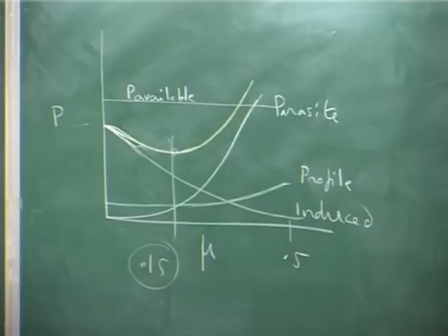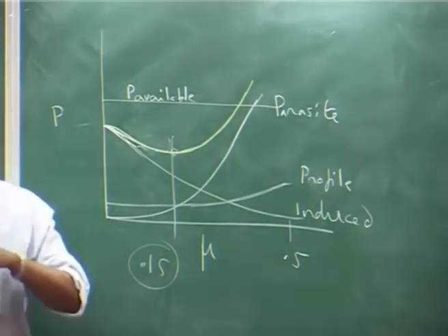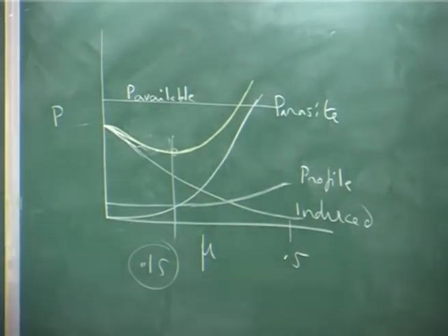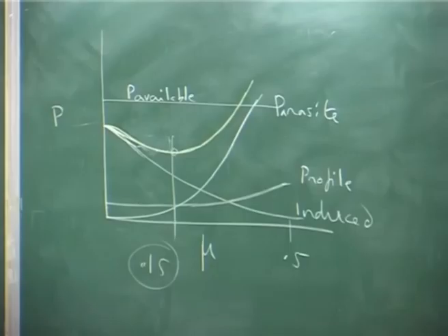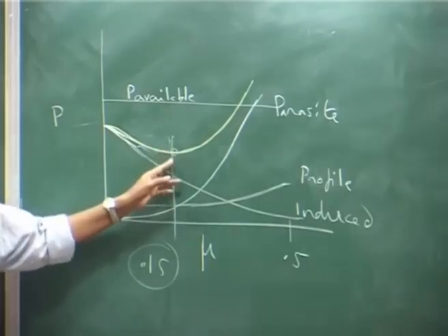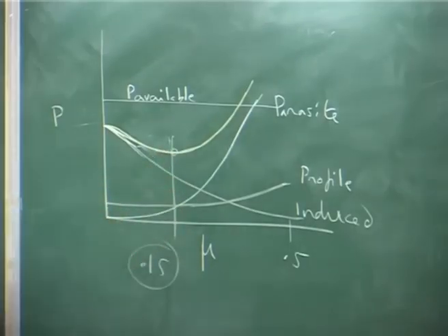But when he comes near the ground, usually what he will do is increase the collective so that he goes up, it is like a braking, he will try to go up and then he will come down. So, auto rotation descent will be minimum when the rotor power required is minimum. Rotor power required is minimum somewhere around 0.1 to 0.15 mu, the advance ratio.